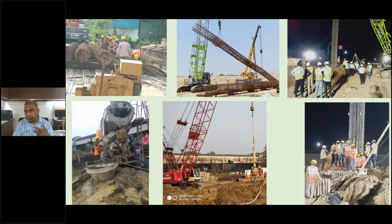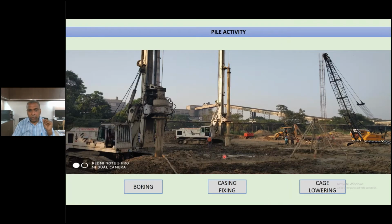Before you insert your reinforcement cage, you have to flush the muck. Take the muck collected at the bottom of the borehole by baler, and then you have to flush it with the bentonite slurry until the density of the bentonite being inserted is the same as the density of the bentonite coming out. So that is also a very messy operation. This is the whole procedure, and you can see here how messy it is.